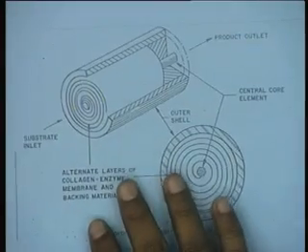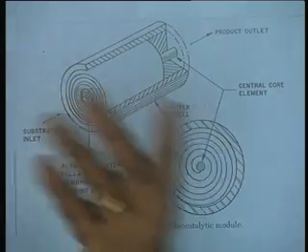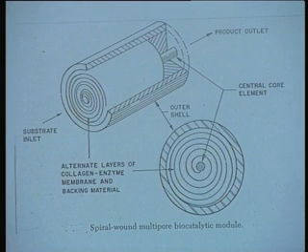It operates almost like a packed bed system. Only, instead of packing the column with particulate material, the film is wrapped around a core spaced by another sheet, and then the whole core is inserted into a column. So you can feed the substrate either from the top or the bottom and take it out as another stream. It's almost like a plug flow reactor.